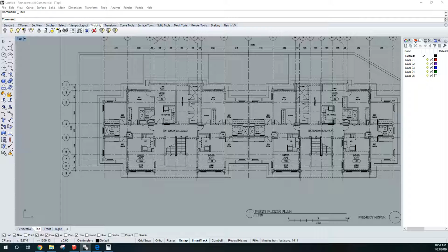Save. All right, hopefully that explains how to do it. We're basically importing it, getting the line work in there. We're scaling all of it by a decimal based on a dimension string that we measure, and then take a percentage of and scale about that percentage.